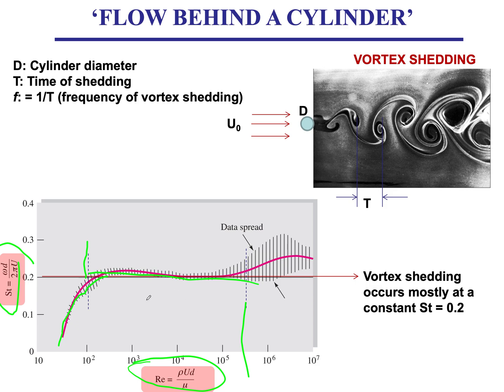So the conclusion of this plot is that once you're beyond the viscous region, with your Reynolds number above 100 or 1,000, the non-dimensional frequency of the oscillations of these vortices becomes constant. And for us, this non-dimensional frequency is 0.2. So now you can take this picture to the bank and use it in your engineering problems if you want to evaluate at which frequency your object oscillates.